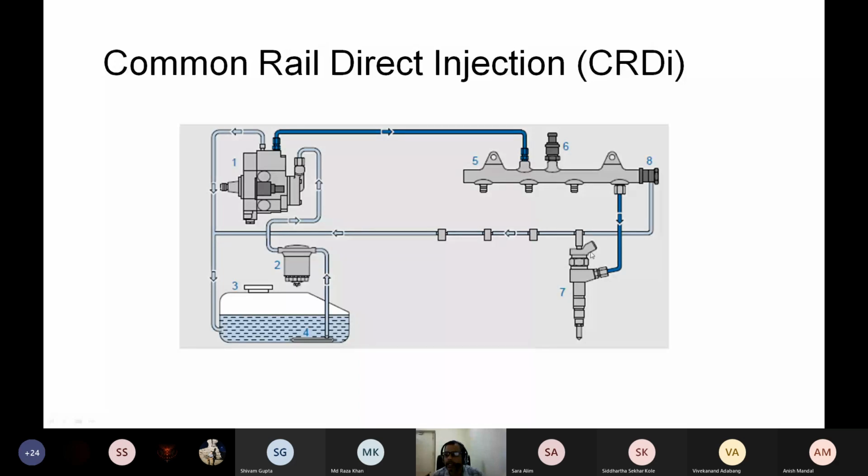The injector is a solenoid based injector. So as soon as the injector receives the signals, the plunger will move up and fuel injection is going to take place. In that way, it can control the start of injection. Since we have control over when we want to open the injector, we can send the signals 2-3 times in one cycle to the injector to open it. And in that way, we can control the multiple fuel injection system also.